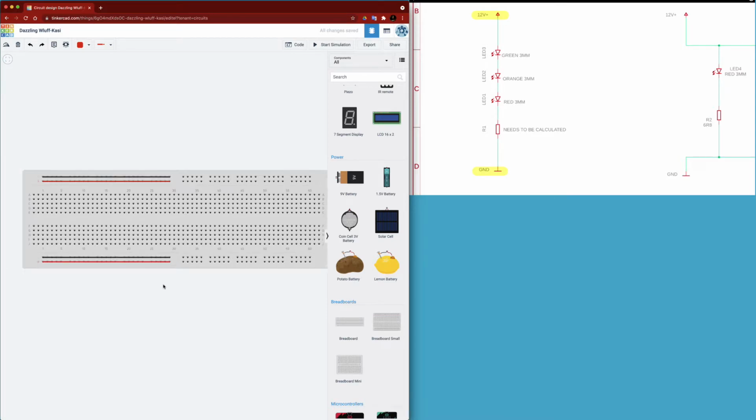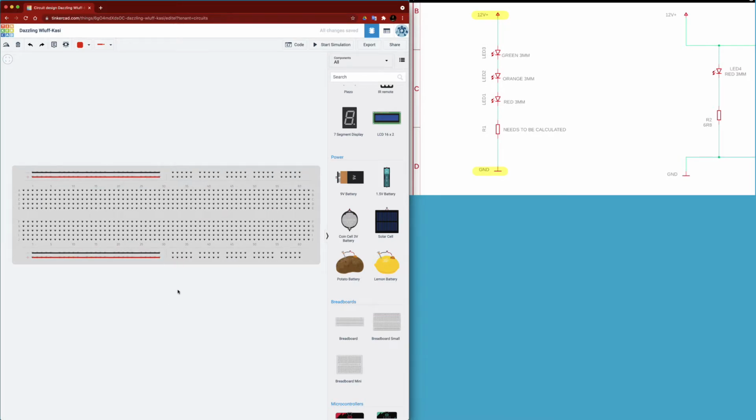Now essentially the board is sometimes split into 4 little sections. You have this section up here on the top left, then the bottom left, and we've got the bottom right and the top right. Notice that the gap right here is a lot bigger than these other gaps going between in here, which indicates that those are not connected. So in order for me to connect the left and right sides of the boards, what I want to do is put a jumper in there.